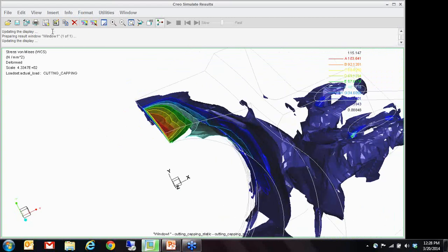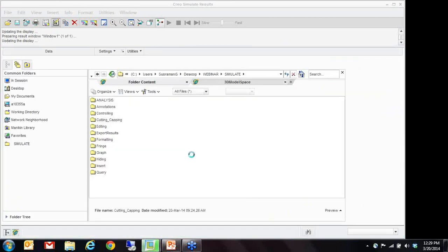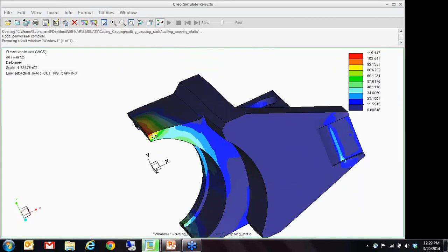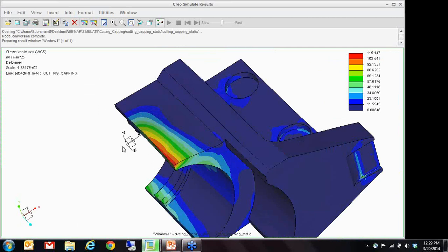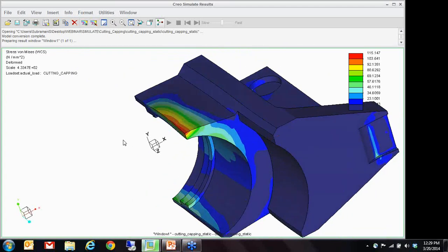This is very important because what we are generally looking at is the picture from the top, which is, hey, I made some colorful pictures, this is what I got. But you're looking at it only from the top. Now, doing the ISO surfaces and contour, you can actually see the depth of the stress or depth of displacement of any measure that you want.